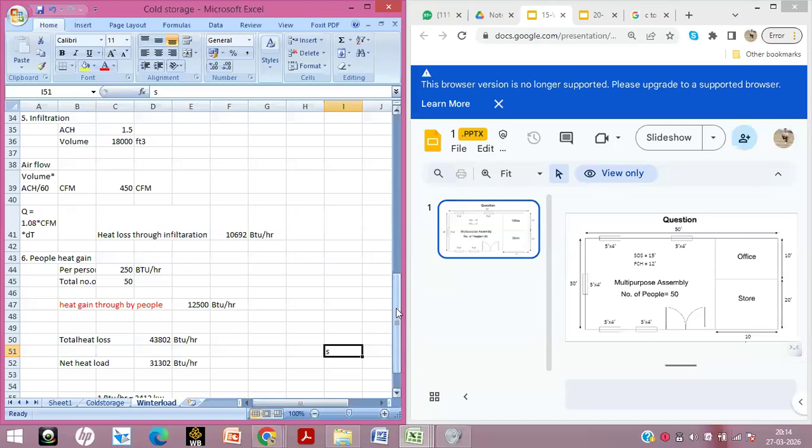So in this case, should we use this formula only? Yeah, because for our heat load calculation in the previous meeting we also used the same formula, volume into ACH by 60. But we have also written it as fresh air CFM equals CFM per person into number of people plus CFM per square feet into area, the heat load.